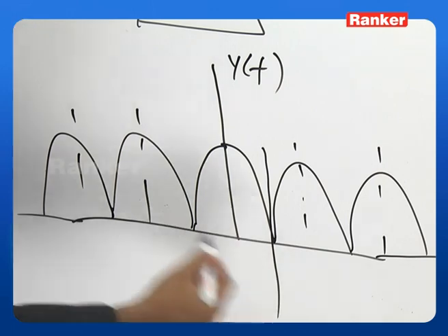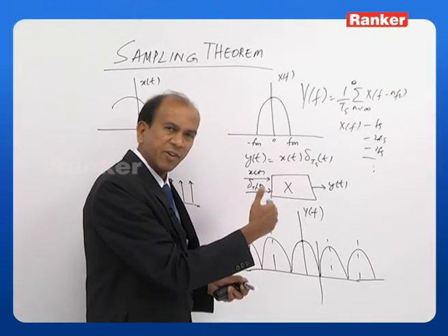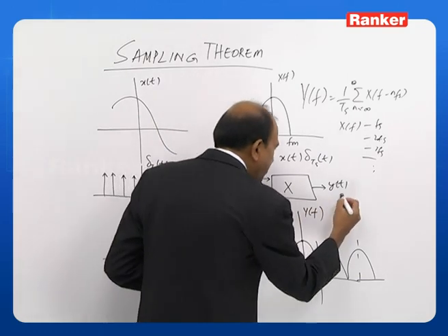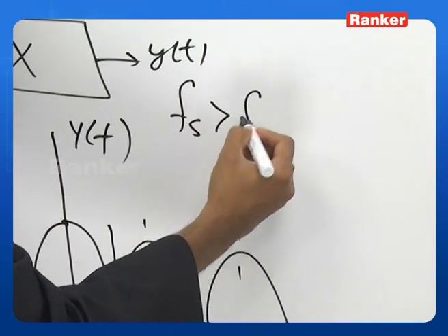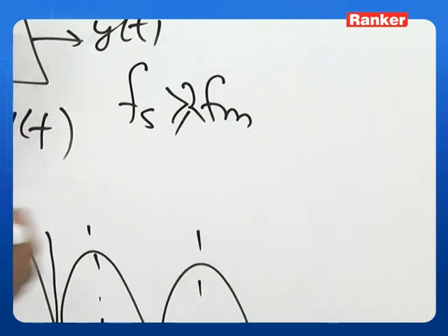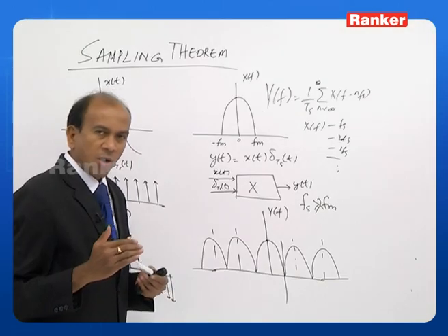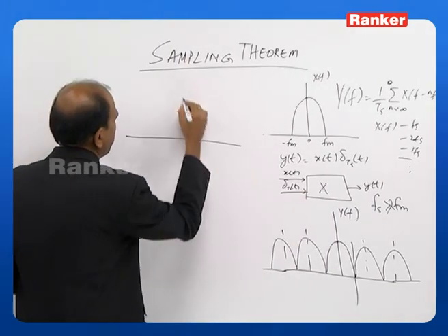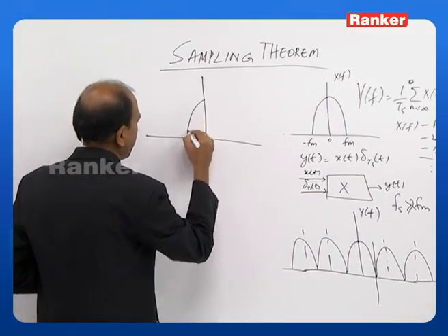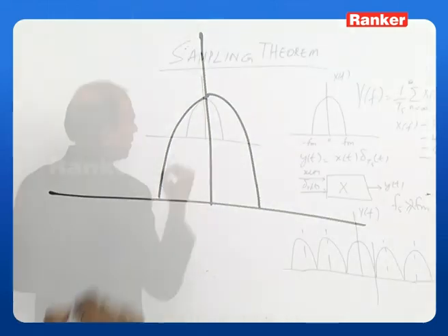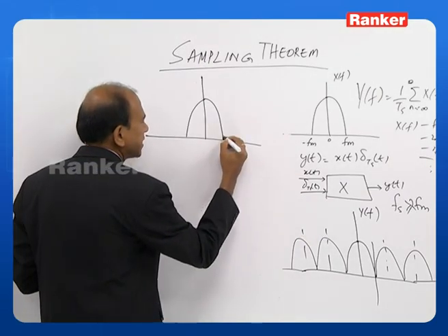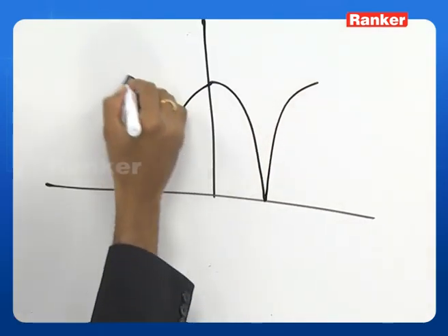So, here the first one is ending and immediately the second frequency is repeating. This is possible because we have taken the sampling frequency as greater than 2fm, fs greater than 2fm. So, once this condition is satisfied, there is no overlapping. That means, if you look at this here, Fs greater than 2 Fm, you have this, and then second one is starting exactly where this is finished.